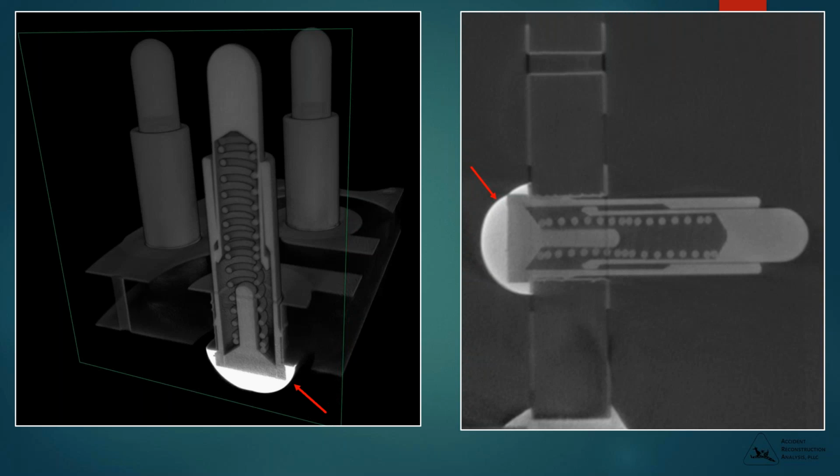And again, as Ben points out, these are through-hole components, and it shows a lack of solder penetration into the through-hole connection. The final point to make is that the client determined that these pins are actually supposed to be surface mounting components rather than through-hole components.